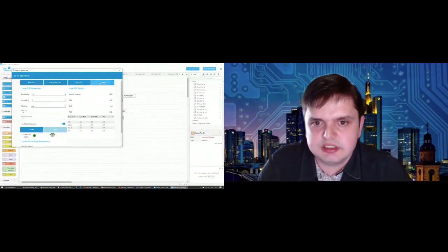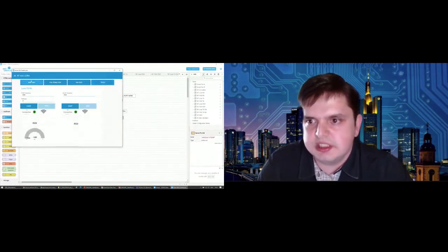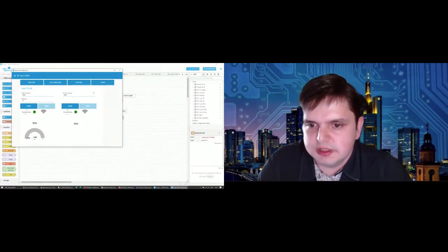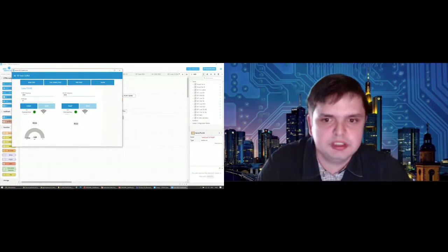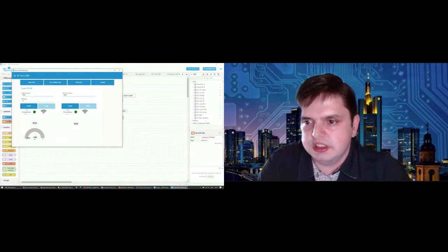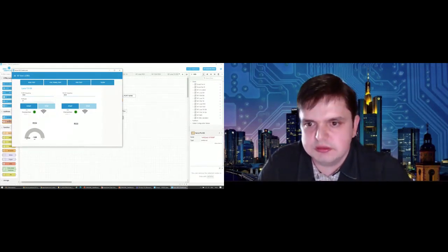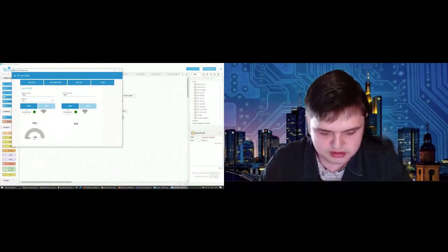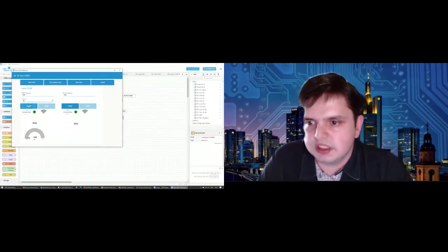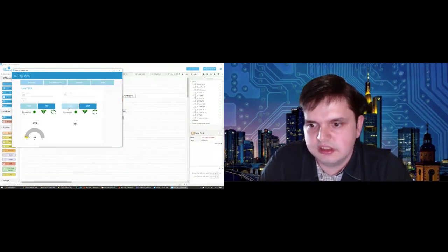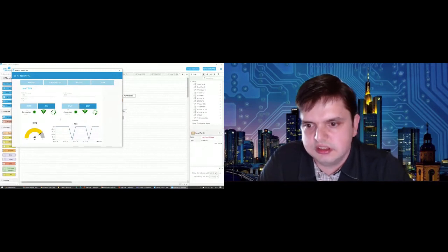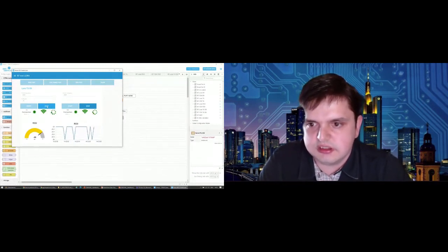Now for the last test, that is the TXRX, that is basically again the RSSI test plus tone test, but this time we use two boards. So for example, in your development, you can use the STM32WL Nucleo as a base board, and the other board would be your PCB, which you want to test if it's behaving as it's designed. So again, I start the test, and I can see I'm receiving the signal. I can stop it.